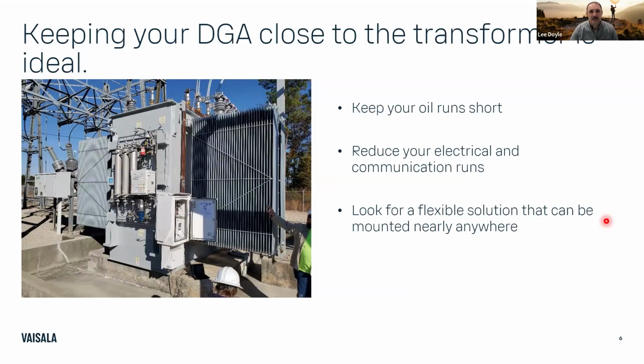I wouldn't recommend that, only because it's really going to depend on the location that you're pulling the sample from. And if you can pull from the main body of oil, that's always going to be much more preferred than getting into an oil filtration system, because sometimes they can have, I think this one was focused on moisture, but some can have the ability to outgas a bit. So you may not be capturing the trends correctly, in particular if that's the case.